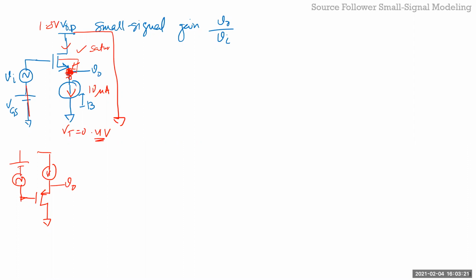So let's say I bias VGS equals 0.9 volts. Obviously the AC part is 0. So the gate is 0.9 volts. What will be the source voltage? It'll be 0.9 minus 0.4 plus some V effective, whatever it is. So it'll be a little smaller than 0.5 volts. This will be around 0.5 volts, right? For argument's sake, let's say it's just VT.